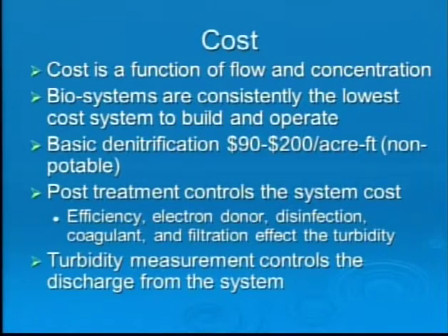And I think we found the majority of the work that we were addressing at our site in West Valley was focused on getting the turbidity to that 0.3. And everybody says, hey, that's being done on all these different post-treatment systems across the country. But believe me, most of the time we spent out on that system was not removing nitrates. It's addressing the concerns of the post-treatment and getting the turbidity where we wanted it.